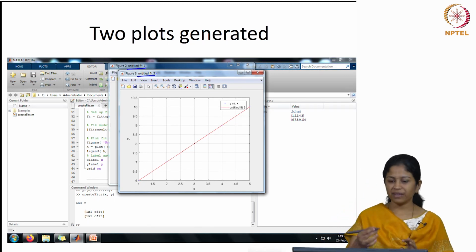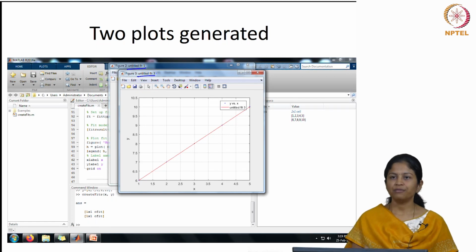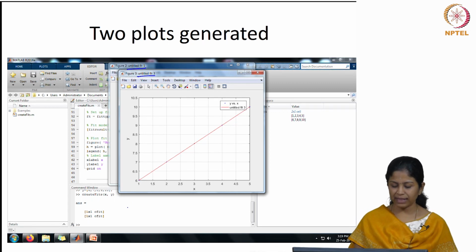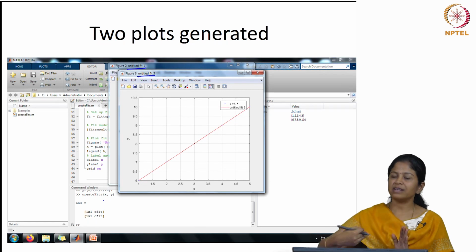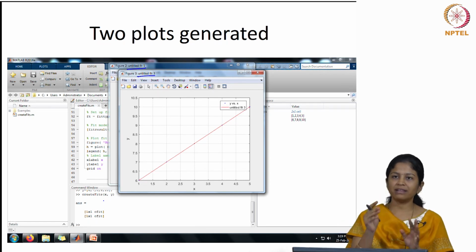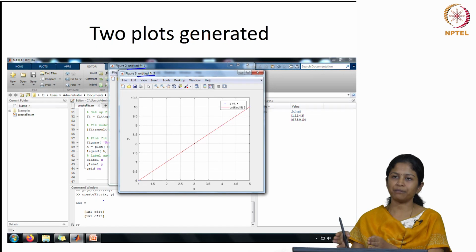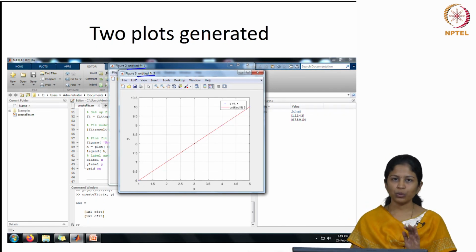This is because previously when we saved the session, we saved it for two different fits, because in the lower tab you would have seen that there were two fits which we have done, and it has actually saved whatever was there in its memory. So when you generate the code, you should remember that whatever you have done in that session, from opening that curve fitting app, everything will be in the memory. So once you finalize your procedure, you just do the exact procedure, then if you generate code, it will be convenient. So I have just shown this here to illustrate that particular aspect.